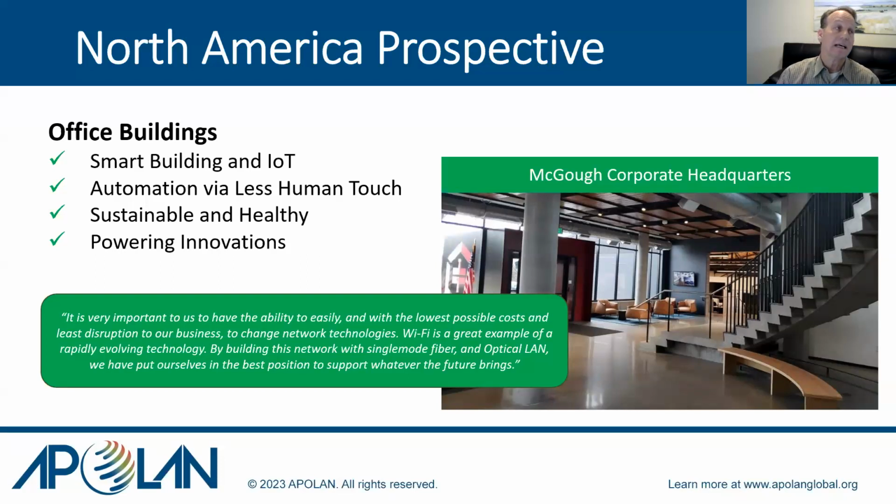Last, we are very excited about powering innovations, and that comes from class 2, class 4, and microgrids. So from a class 2 powering standpoint, now we're connecting ONTs 2,000 feet out and then adding the PoE out another 300 feet. That's possible with class 2 remote powering. Now with class 4 fault managed power, we are truly unleashing the fiber-based LAN, and those ONTs can now go a mile out. So it really helps with design flexibility for these smart buildings.